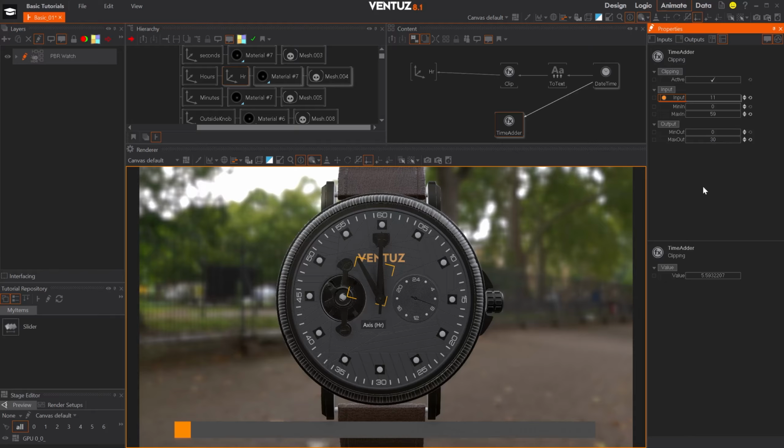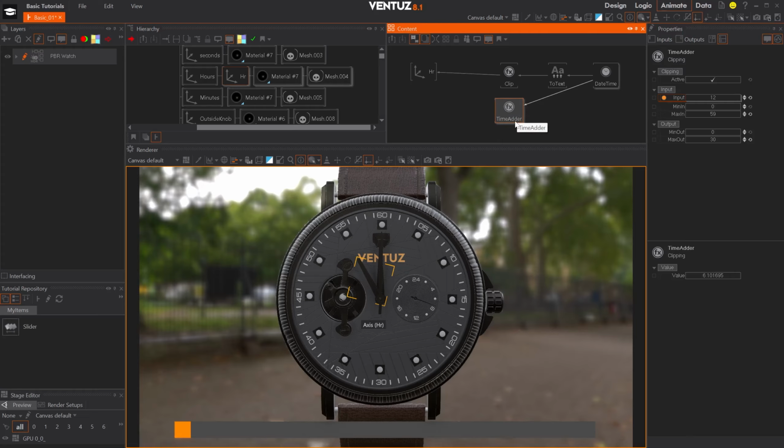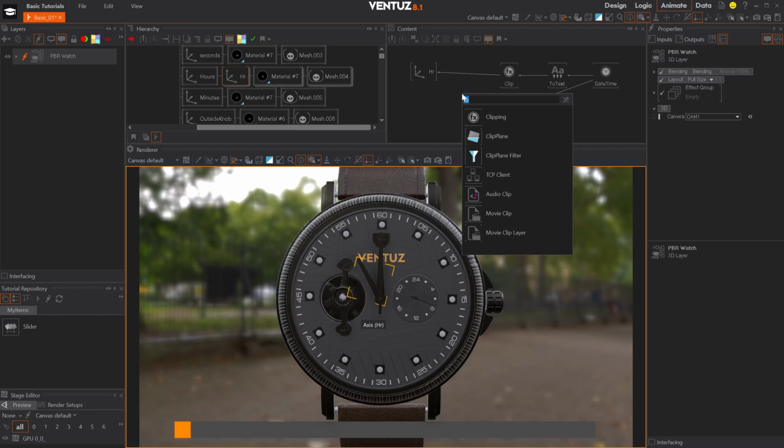The last thing that we are now going to do is subtract this new value from our current one here. Since we are going from 360 to 0, we can't add it but have to subtract it to have it move in the correct way. To do this, we are grabbing ourselves an integer expression node. They can be thought of as mini C# functions and follow the C# syntax.